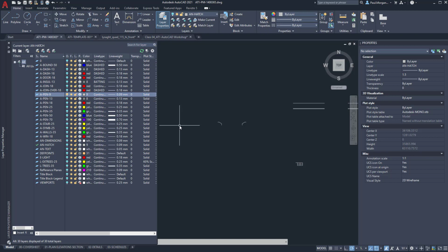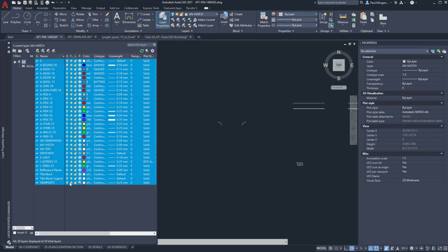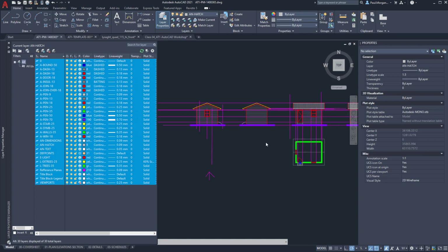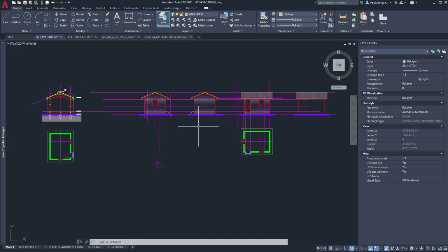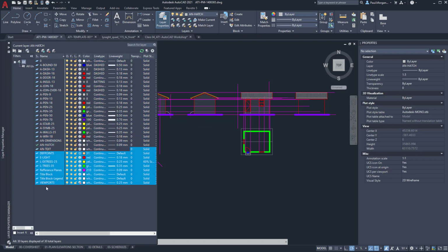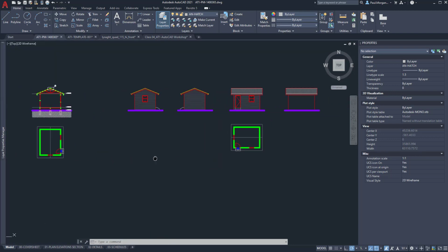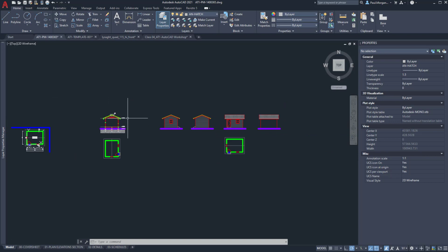Or the other way to do this is to go in reverse, and sometimes the reverse is a little bit easier, where you turn everything on and you start turning things off one by one. A good example, we'll start with guides. I'll turn off the reference planes, and I'll make sure that I don't have any floating reference planes still in the drawing. Clearly I don't, so that's good.